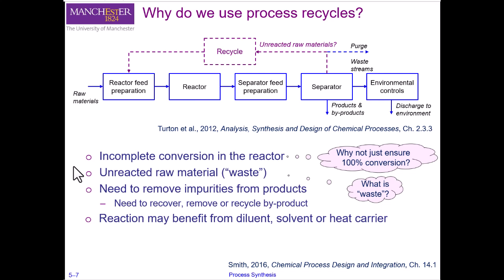Note that while the waste can be a problem, many undesired byproducts do have a value, maybe not very high value as a product, but they can still be used as fuel or as feedstock to another process. The high cost of reactants often makes it essential to recycle streams, but recycle streams sometimes also recycle components other than reactants, for example, an impurity in the feed stream.